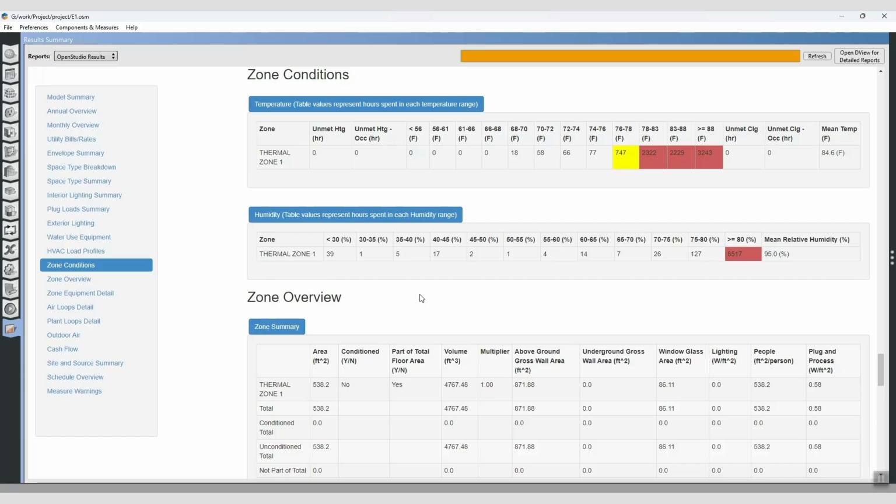After adding occupants and equipment to the space, the results indicate a significant increase in the number of hours with very high indoor temperatures. In particular, the time spent above 88 degrees Fahrenheit rises dramatically, highlighting how internal heat gains alone can push the space into uncomfortable conditions. There's a benefit in some cases and climates, however. Those same internal loads slightly reduce the number of extremely cold hours over the year. But here, the overall thermal comfort clearly worsens.